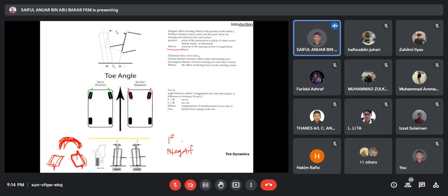Okay, rear tire. It turns out when the person checked this one, they had actually put an excessive camber angle for the rear axle for the Perodua. So they did the correction, they corrected the issues. I think the facelift version already addressed this issue, but the previous batch of previous owners suffer from this issue.